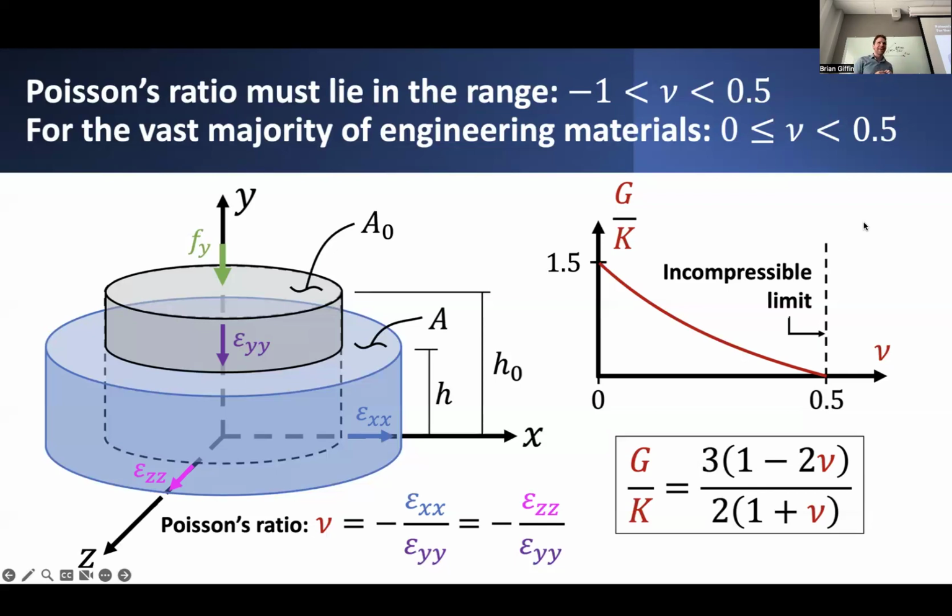There are a lot of materials that behave like this. Rubbers or other kinds of polymers of that nature. Water is usually characterized as an incompressible material. It has a relatively large bulk modulus, and by comparison, the shear modulus is very low. So it deforms in this funny way, but it overall preserves most of its volume when it deforms. Such materials characterize this incompressible behavior.